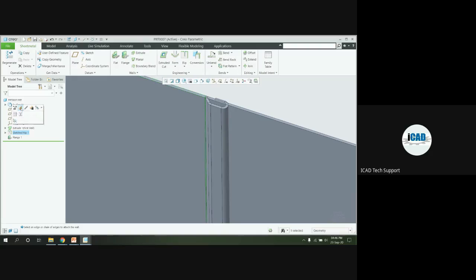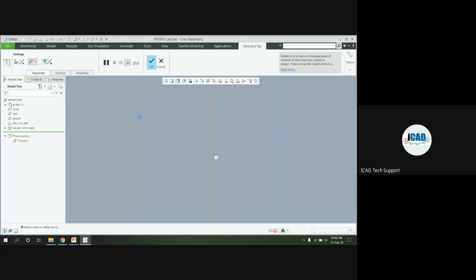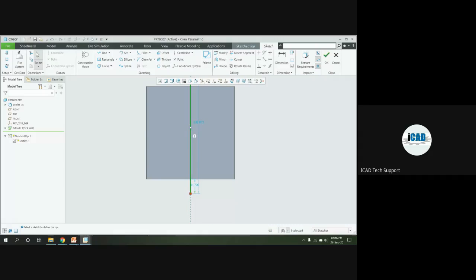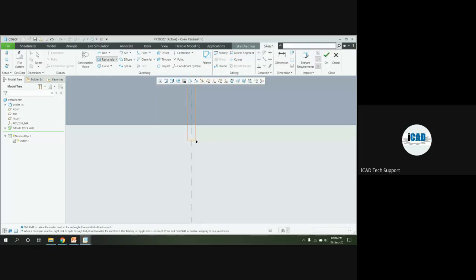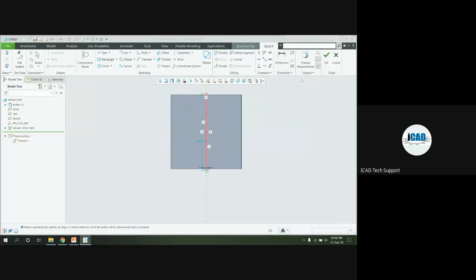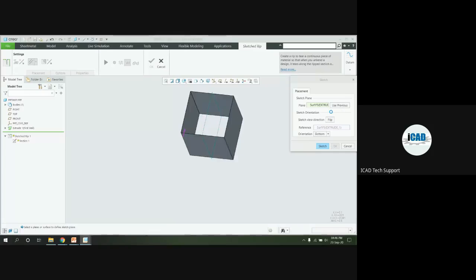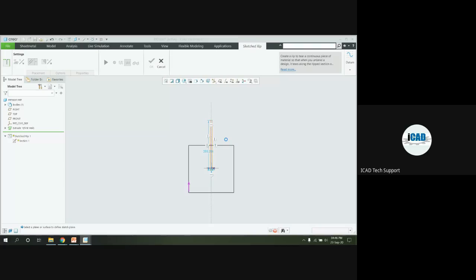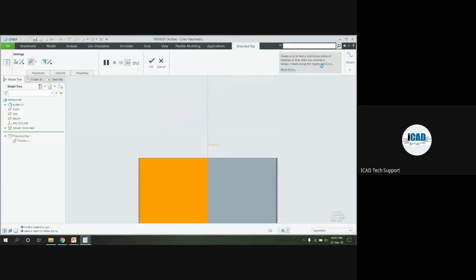I can use this sketch rip as a solid. I can create the gap again. Click on the rectangle, and you need to create this type of gap. A 10 mm gap you can create. Sorry, redrawing it.